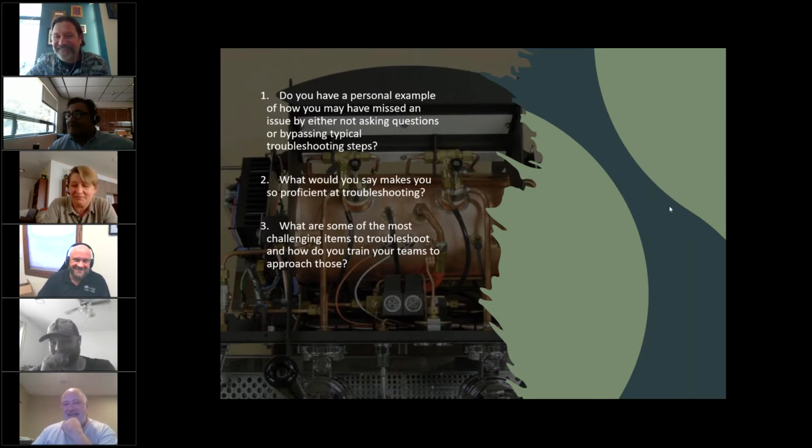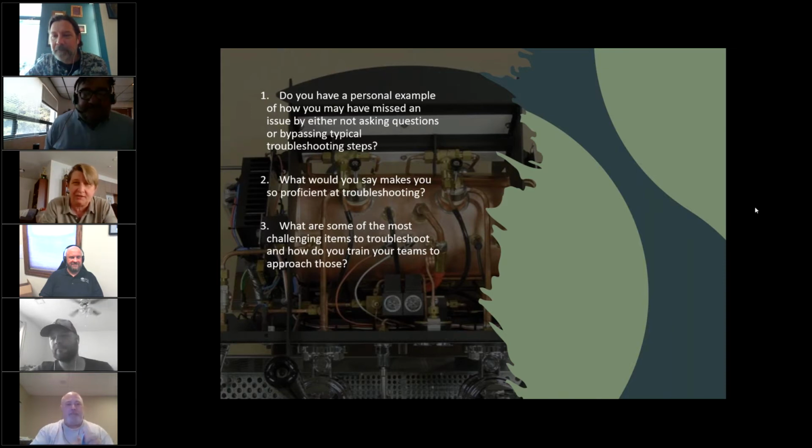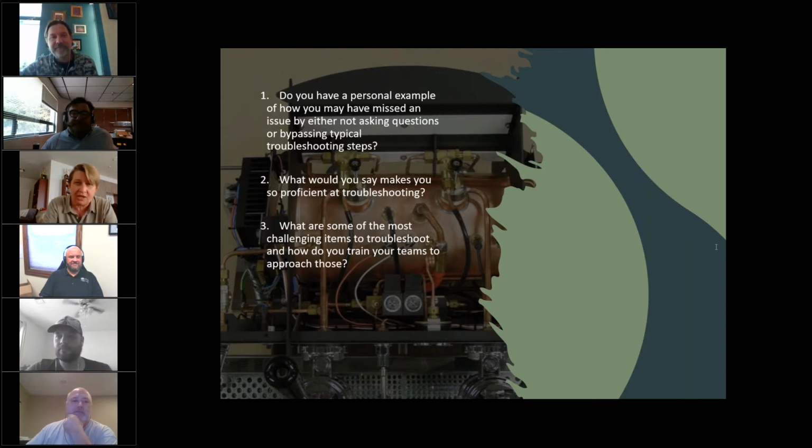Of course. So the pressure relief valve is a safety device. It releases once the boiler pressure reaches that pressure. So is the boiler overheating or has that part failed? More than likely the boiler's overheating, so you test that circuit, which means starting with testing the health of the element with your meter, and then going back to the other components that are responsible for sending power to that element. Are they working or not? And again, that is with meter and also visual inspection.